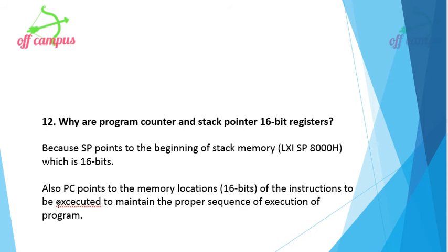Let's see what the program counter is. What is the working of the program counter? It points to the address of the memory location, the next address of the instruction to be executed, to maintain the proper sequence of execution of the program. Actually PC points to the address of the next instruction to be executed. So that is also related to the address bus. So address bus is here 16 bit. So program counter is also a 16 bit register and stack pointer is also a 16 bit register. So the question is why are PC and SP 16 bit registers?